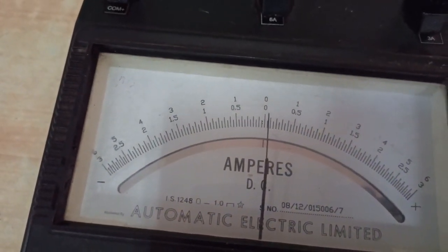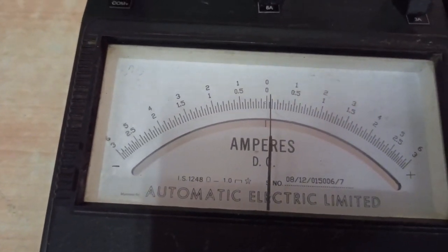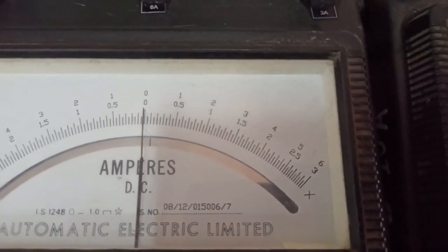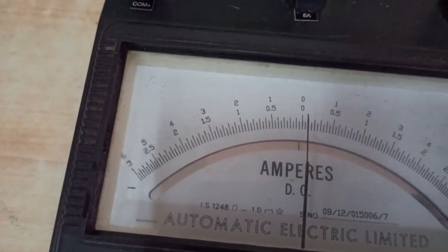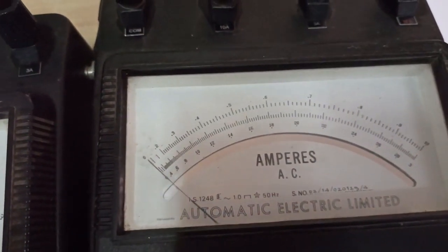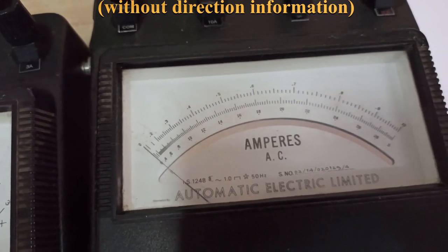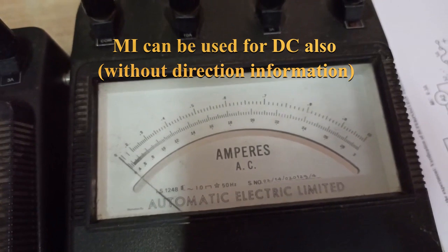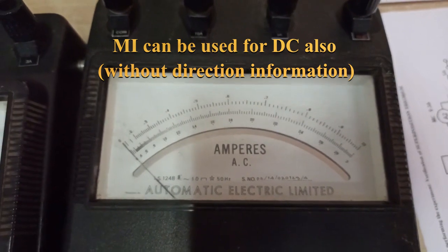Another distinct difference is that both the positive and negative directions of current can be observed on the MC display. You can see the 0 is at the center position, and on the right side we have a positive display for current, and on the negative side it will show you if the current is going in the reverse direction. But for the MI type instrument, the 0 is on the left side, so it gives us current in only one direction. Basically this is used for AC, where it gives us the RMS value of the current, and for AC we are not interested in the current direction, because it changes in every half cycle.